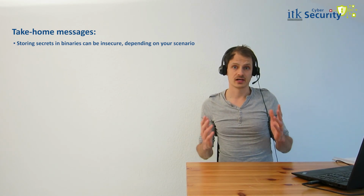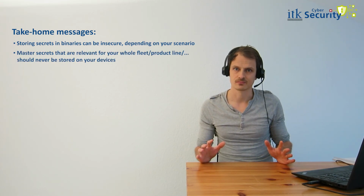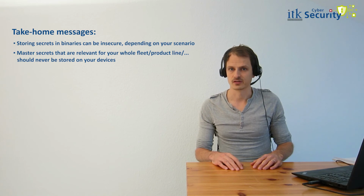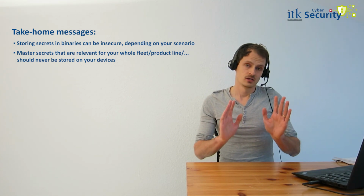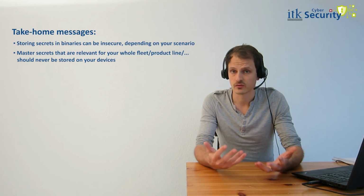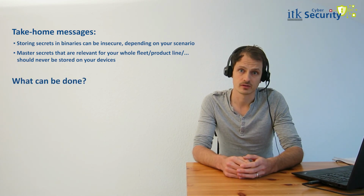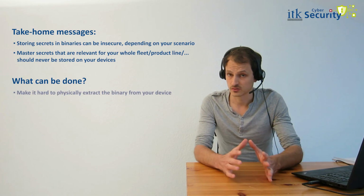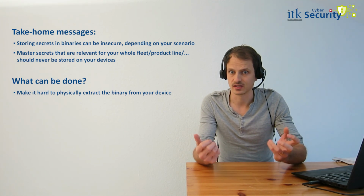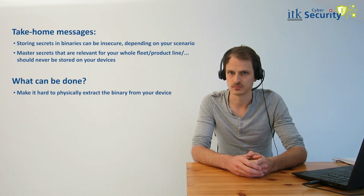And what is also clear, regardless of what the answer to these questions is, never ever store master secrets on your devices. It is bad practice and it will lead to complete security failure if one device is compromised. So never do that. So what can we actually do? Well, for one, you can think about how to make it harder for the attacker to extract the firmware in the binary. Maybe store it in a highly integrated system on chip where it's hard to get the firmware physically out. Don't store it on an external flash memory chip that you can just read out on the PCB or something like this.